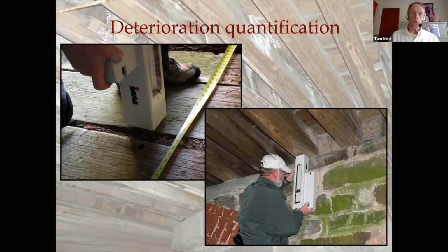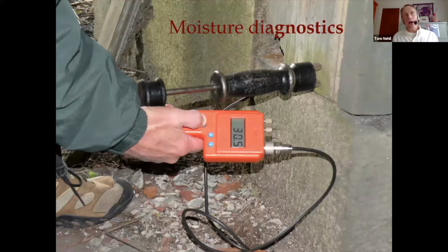So a more accessible tool is simply a small cordless drill with a 1/4 inch diameter tapered bit on it. And so we can drill into a timber and just subjectively assess how hard is it to push in, where does it get easier, what is the quality of the shavings coming out? Are they nice and rich and full, or are they dusty or even nothing coming out? Well, that's an indication of trouble in those cases. So that's looking back at damage that's already happened.